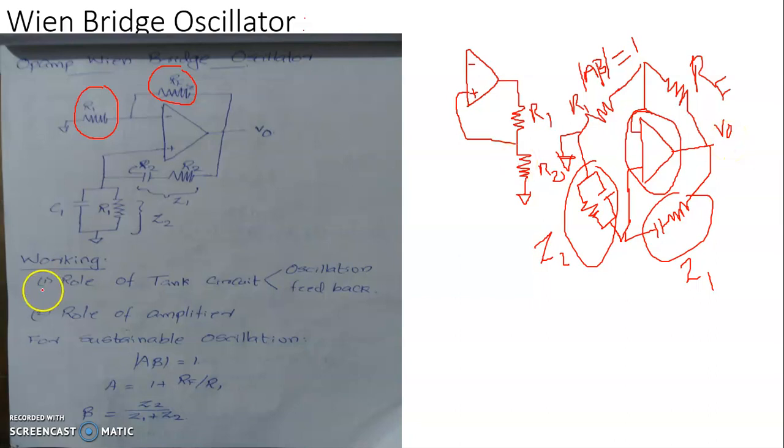How this oscillation arises and the working of the circuit, we will now look into. So this is about the configuration. The Opamp is in a non-inverting configuration actually, and it has a positive feedback also. A part of the output energy appearing across this impedance Z2 is injected to the non-inverting terminal, so it's a positive feedback. And to the non-inverting terminal, this capacitance resistance parallel resonance circuit already produces a sinusoidal oscillation that is being given. So a signal is already given to the non-inverting terminal.